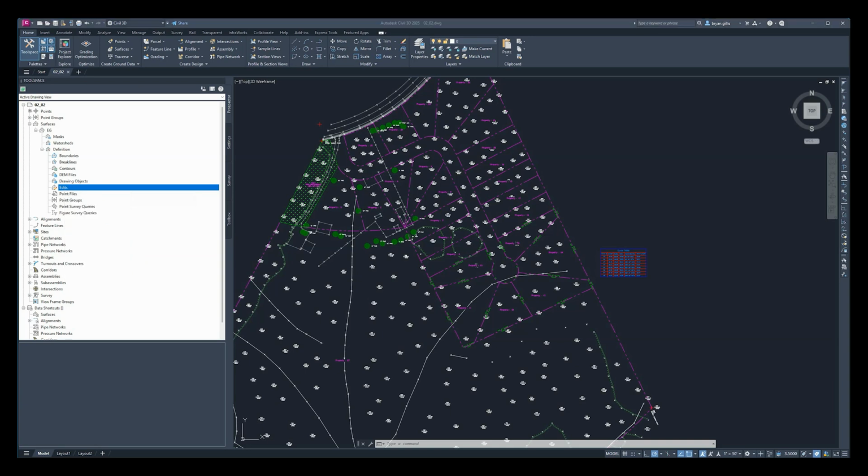So most of those edit operations are going to be pretty obvious in what they do, but I do want to talk a little bit about minimizing flat areas and smooth surfaces. When we talk about minimizing flat areas, first, what is a flat area? Because these are generated surfaces, there's always a potential for error. Sometimes we will have one of our TIN triangles actually be created from 3 points along the same contour line or the same elevation.